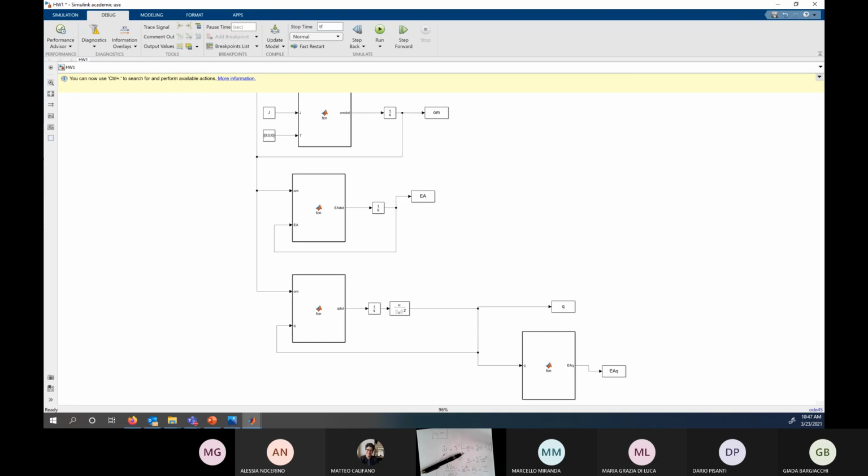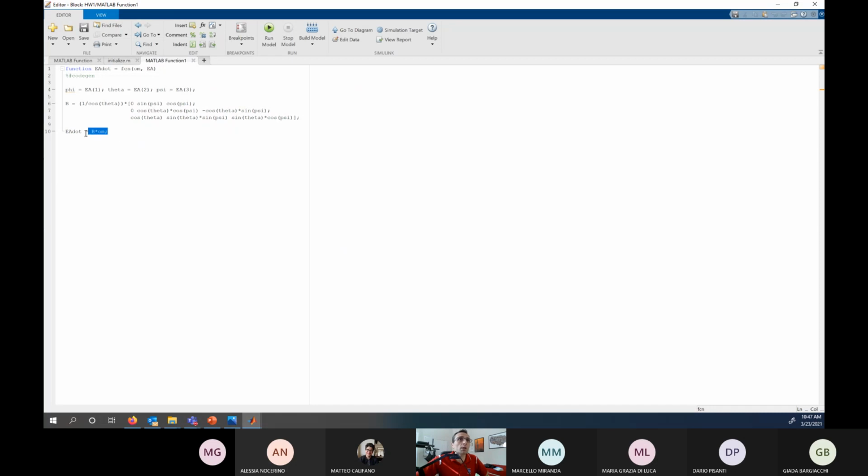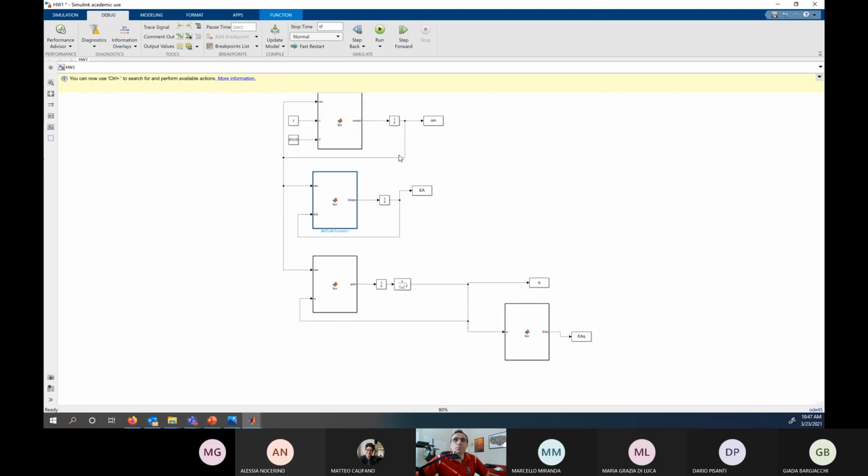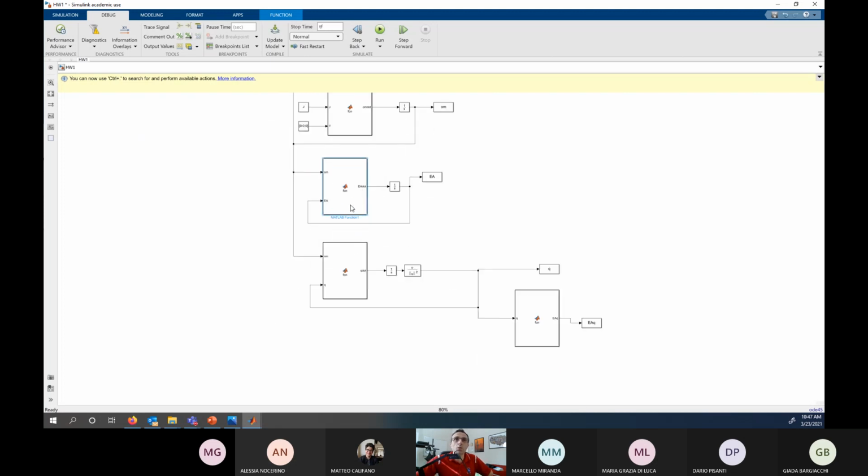Any questions on Simulink? No questions. So what I really want you to do is to basically build. Oh, and one thing to notice, now that we have Simulink open, notice that omega is also coming into this second function, because without omega, I wouldn't be able to perform the last operation, which is the product of the B matrix and omega itself, of course. So as you can see, the kinematics block, this one, needs the information from the kinetics block.